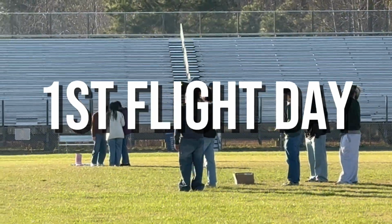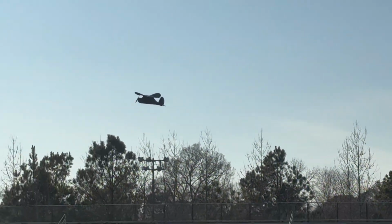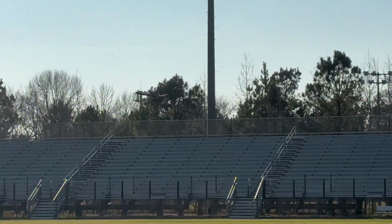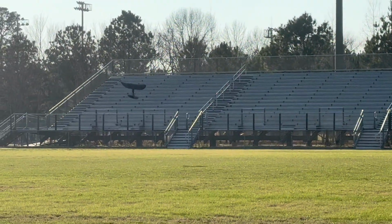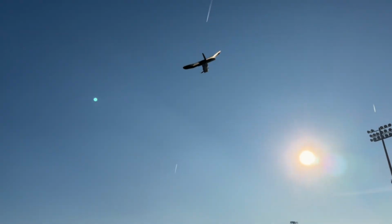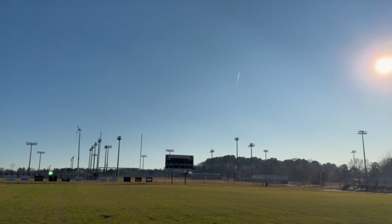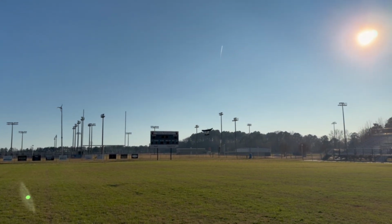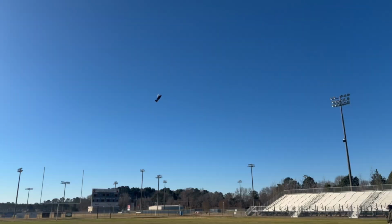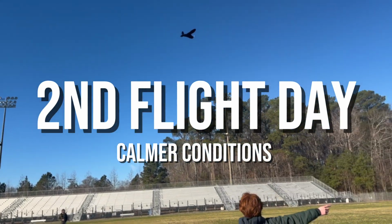We had 2 official flight days. On the first flight day, conditions were extremely windy. Our aircraft was designed as a slow-flying, high-lift platform, and those conditions worked against us. Gusts caused the plane to pitch up repeatedly, and forward progress was difficult because the wind speed was close to the aircraft's airspeed. Even when the aircraft did get airborne, maintaining controlled flight wasn't realistic, so meaningful attempts weren't possible that day. The second flight day had much calmer conditions, and we had 4 official attempts.